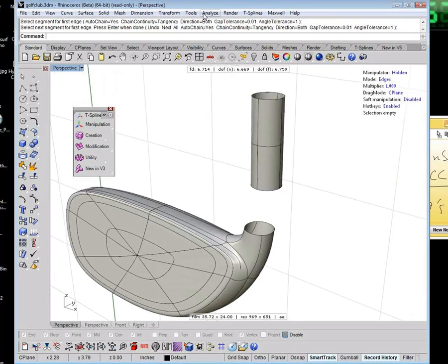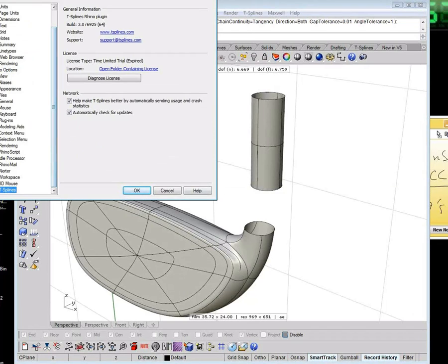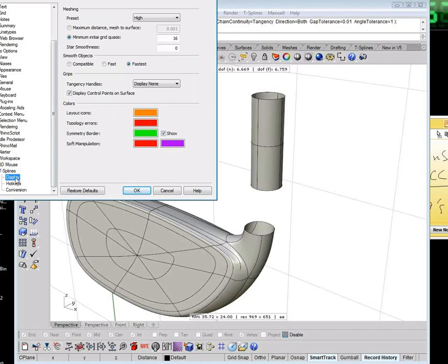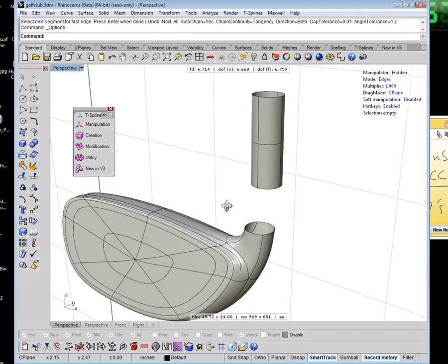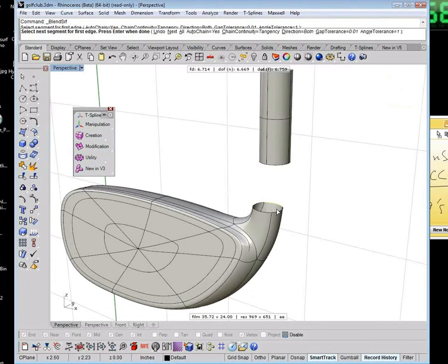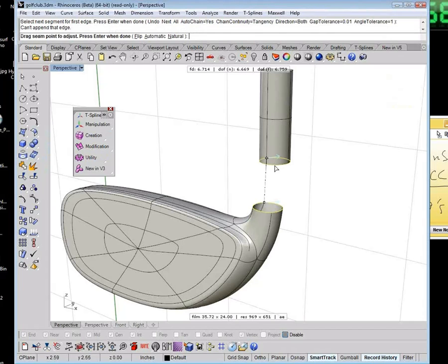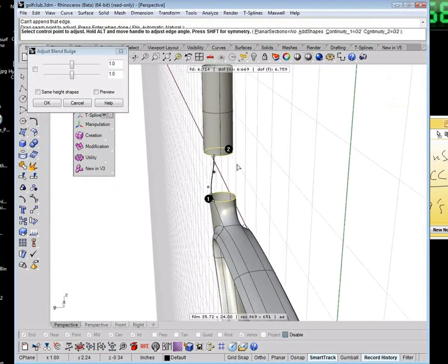If you click on the utility or the options, that would be why it's not. If you click on display, and then, there we go. Yeah, so by changing it to compatible, it's actually displaying as a NURB surface. That way it needs to be in that mode in order to run these Rhino NURBS commands. Got it.